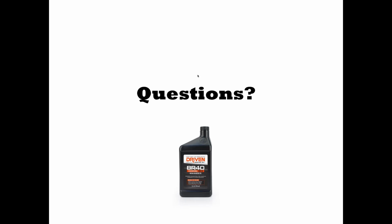Sure. I've got one for you, Lake. Doug has called in, and he's got a couple of questions all wrapped up into one here. Can you comment on a drag race motor, stock limiter racing small block Chevy 350 with 441 heads? The trend seems to be tighter bearing clearances and low viscosity oil to improve the horsepower and lower lap times on the drag strip. What does this do to wear of the engine parts? How low of oil pressure can we go on a drag race small block? Or what makes the most horsepower, low oil pressure versus low viscosity oil and tight clearances?